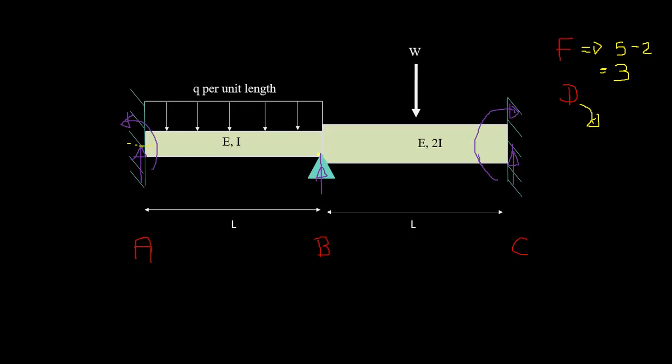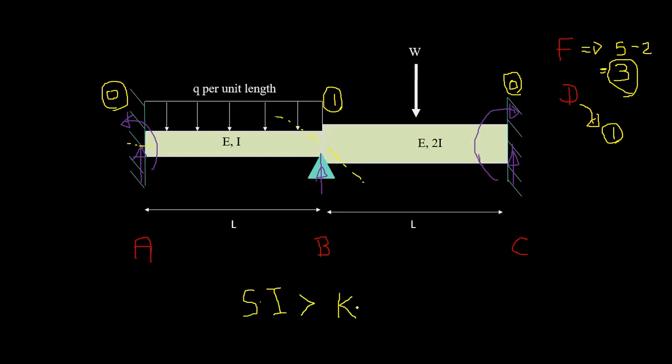Here, this is a pin support. So the only possible thing is it can rotate about this axis, right? So we have 1 unknown. Here you have 0 unknowns, right? Here also the same, 0 unknown. So that means unknown displacements are 1, right? It's directly 1, and unknown forces are 3. So your statical indeterminacy is larger than kinematic indeterminacy, right? So this is Ki, this is Si, right?